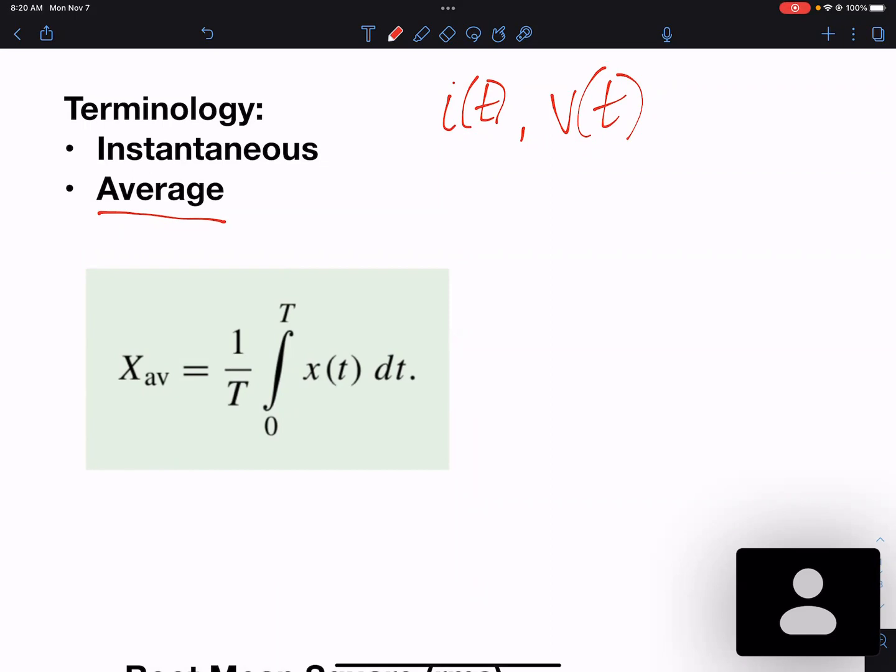So when you think about one period of a sinusoid, what would be the average over a sinusoidal period? Let me draw this. If I wanted to find the average of a sinusoid, what's the average if I'm finding the area under this curve? It'll be 0, right? Because this is going to equal the negative of that. So our average here would be considered 0. Sometimes the functions that we're finding, though, are not going to be nice sinusoids.